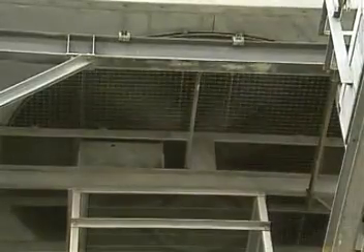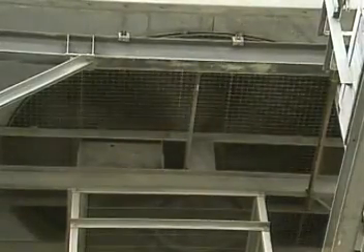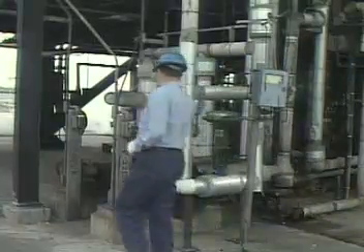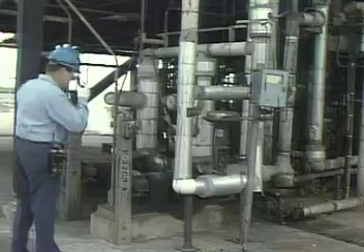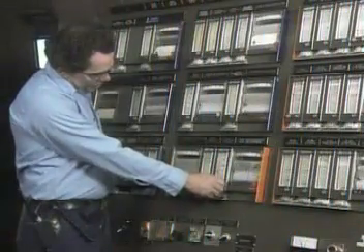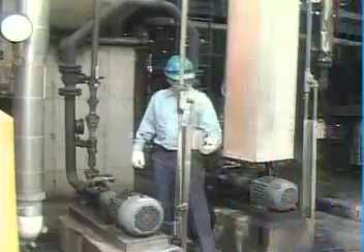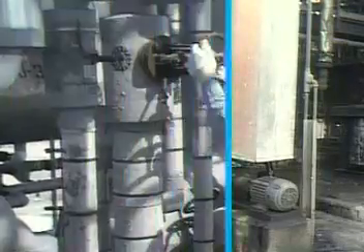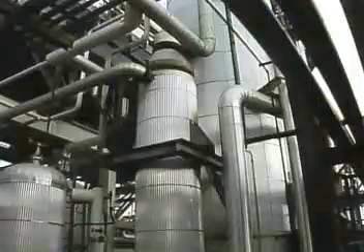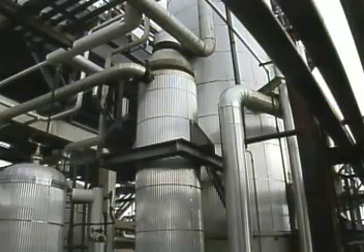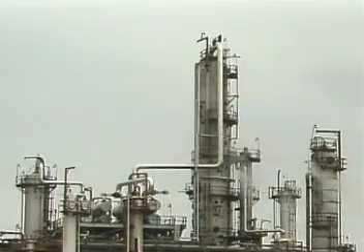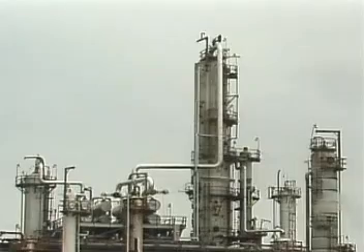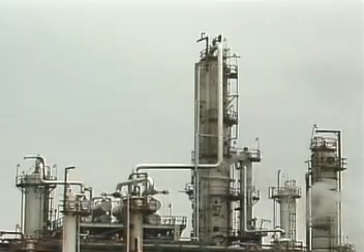Backup equipment may need to be left in operation to stabilize conditions. Once conditions have been stabilized, an emergency shutdown will likely involve stopping the flow of feed mixture to the column, stopping the takeoff of overhead product and bottoms product, and possibly shutting off the reflux system and the vacuum system. Procedures such as draining the column and the reboiler are avoided unless they're needed to maintain safe conditions. Of course, problems that can cause an emergency shutdown can vary, so the exact procedures that are followed will depend on the type of emergency.